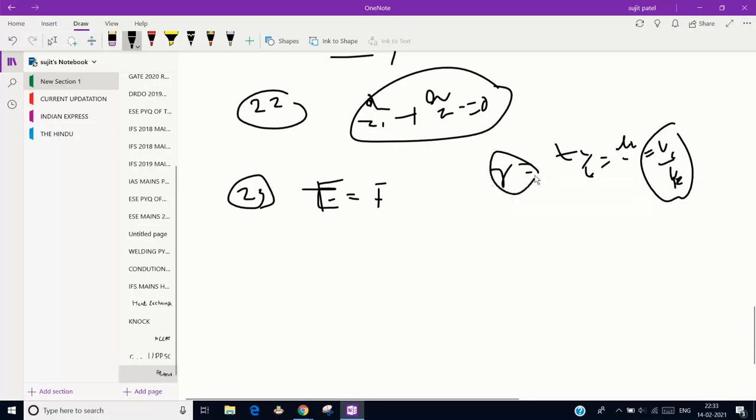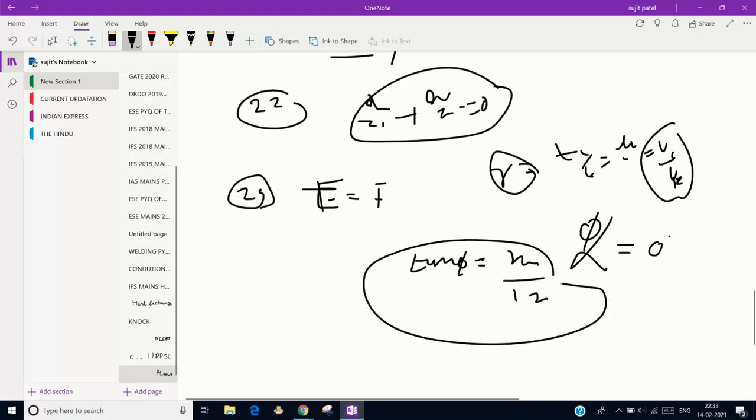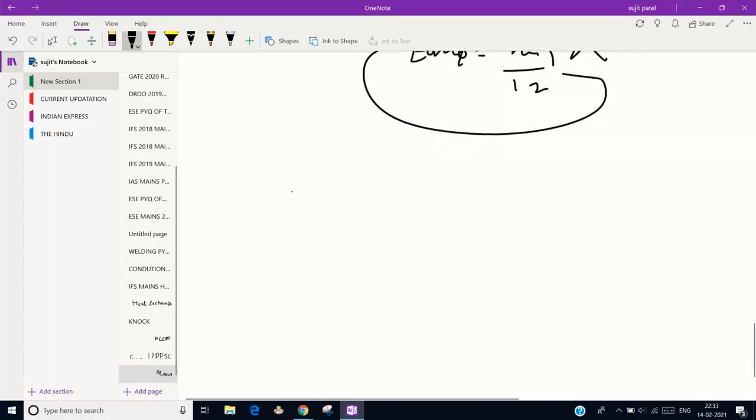So you can find the chip thickness ratio, and alpha is also given for orthogonal turning with zero rake angle. So put the formula, as per Mandal sir, tan phi is equal to r cos alpha divided by 1 minus r sin alpha. Okay, that is the thing, and that is one question of orthogonal turning.